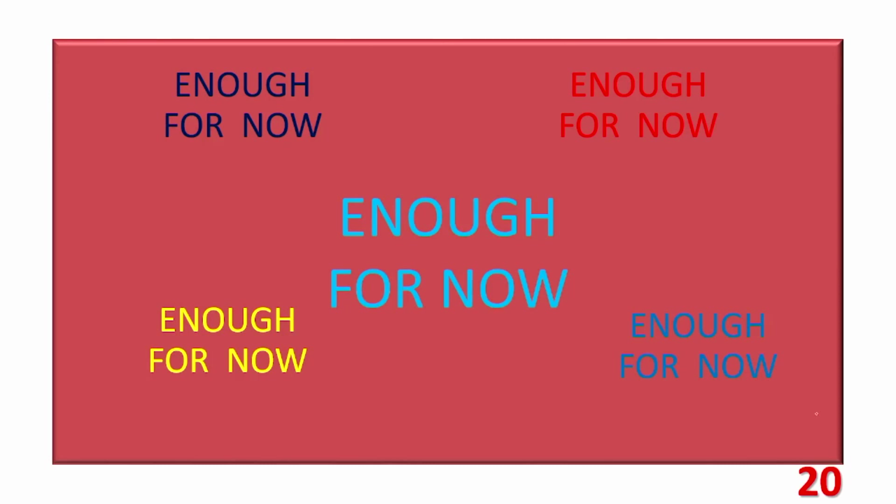In this session, linear arrays are introduced, different modes of operation, grating lobes, different features are all given, described and explained. Binomial arrays are also introduced along with their merits, demerits, in addition to the principle of pattern multiplication. Hope this session is useful to you. We meet again in another session with a new topic soon.